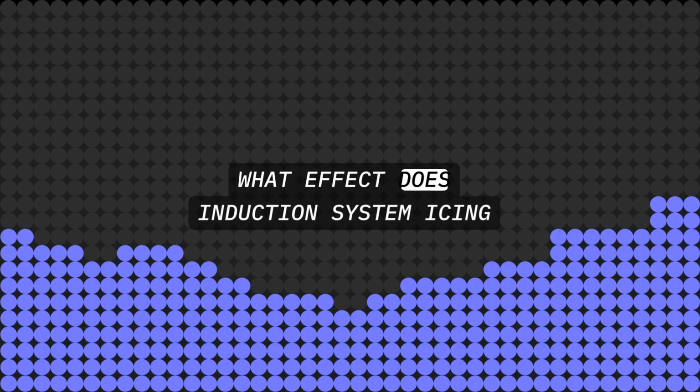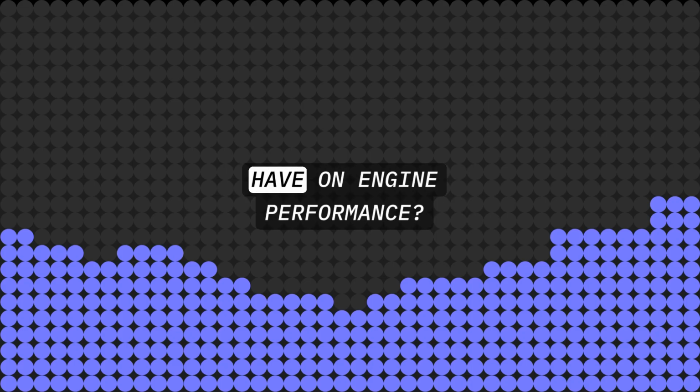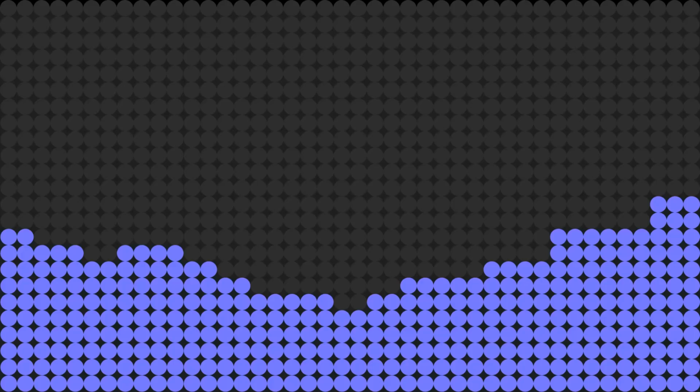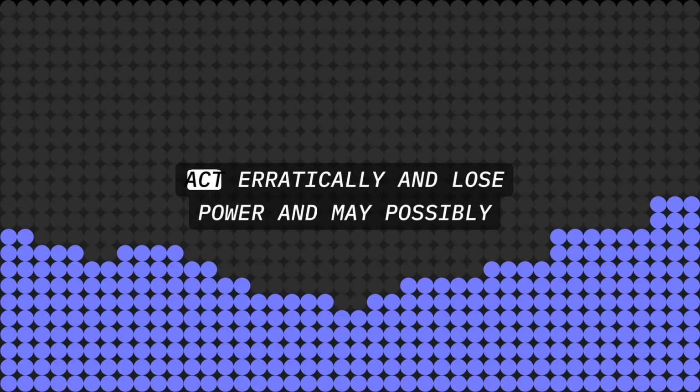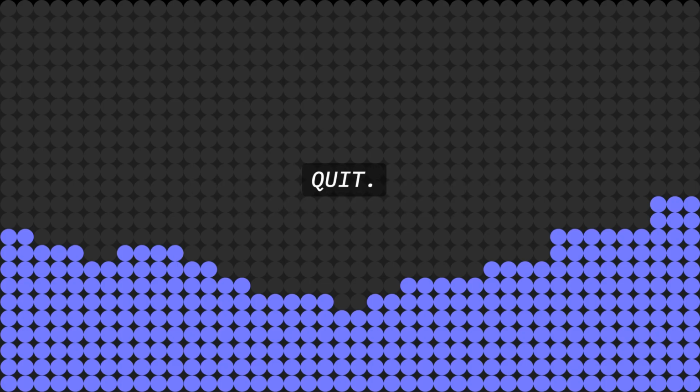What effect does induction system icing have on engine performance? Induction system icing can cause an engine to act erratically and lose power and may possibly quit.